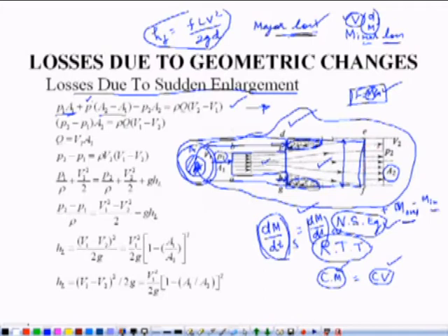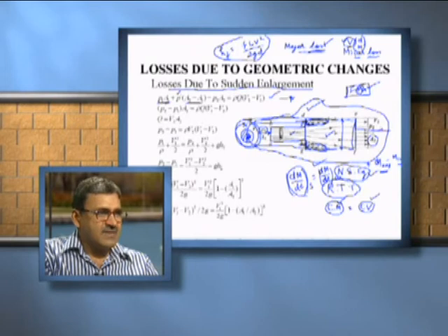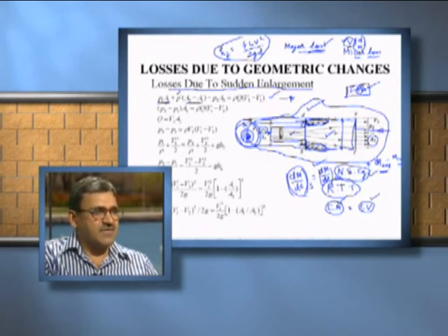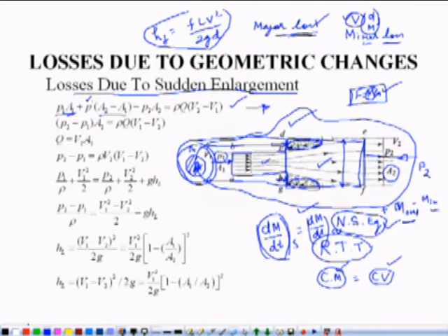This pressure force is acting in x direction, and on this face EF, the velocity is shown with the help of these arrows, pressure is acting in such a manner so that it compresses the fluid. So, pressure always acts, if magnitude of pressure is P2 at this face EF, then this pressure will act in this direction, which compresses the fluid, right. So, we have a pressure P2 into A2, since this is acting in which direction? Negative x direction. So, this is minus P2 into A2.